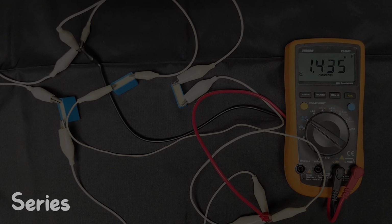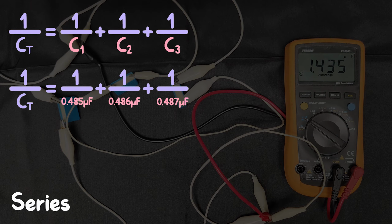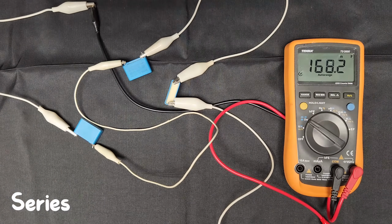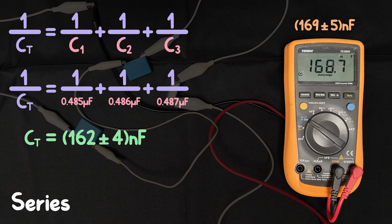When combined in series, the inverse of the combined capacitance is equal to the sum of the inversed capacitance, which would give a capacitance of 162 plus or minus 4 nanofarads. Doing this practically, we get 169 plus or minus 5 nanofarads, once again agreeing within uncertainty.